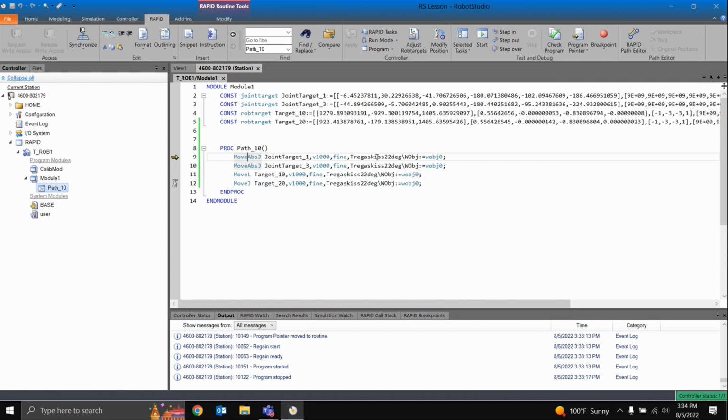The reason it does watch for that is, if I have a stick sticking off the end of the robot that's 10 feet long, and joint 6 is swinging as fast as possible, that means it could be moving 10, 15 meters a second because it's got so much length on it. That's going to be a problem from a safety perspective a lot of times, or just the momentum it'll build up. So it is making sure that wherever the tip of the robot is never goes faster than the set speed.